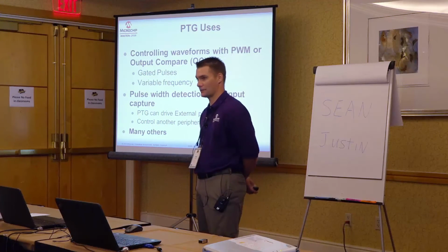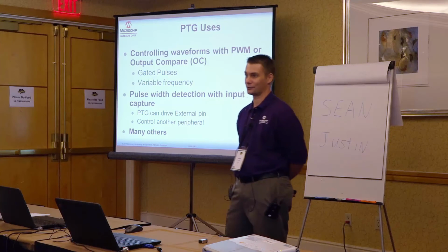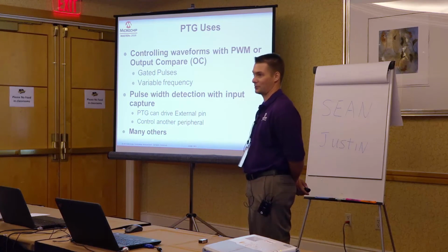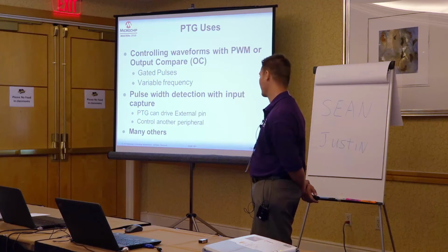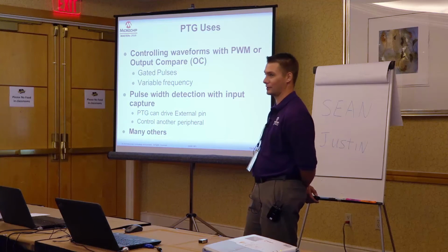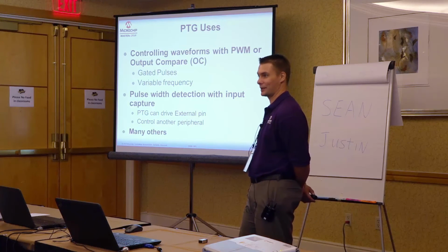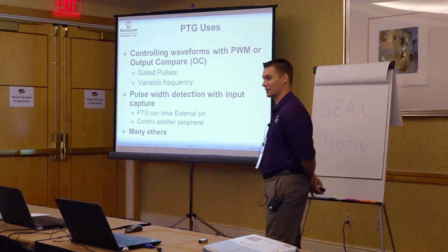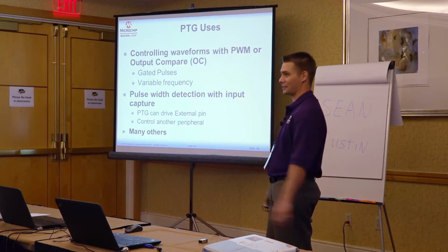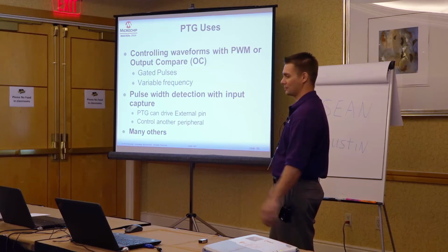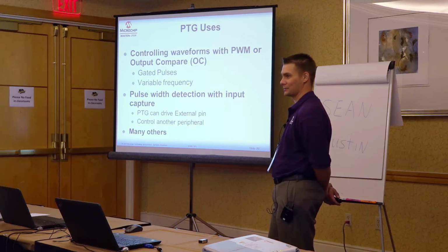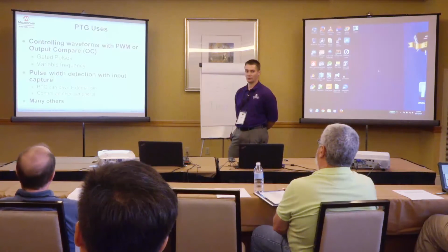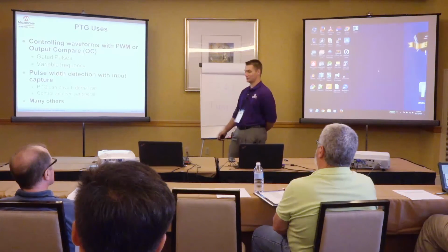And another good feature of the PTG is that it actually will drive an external pin. So you can come up with a solution that is almost external, like hardware, to the part. It can also be used to control another peripheral. Again, that was kind of the original intent with the ADC. And many other things can be done with it. So I encourage you to take a look at these. This particular peripheral, I think, is becoming more important and asked for by our customers. So most all of our new parts that are coming are going to have a PTG in it.